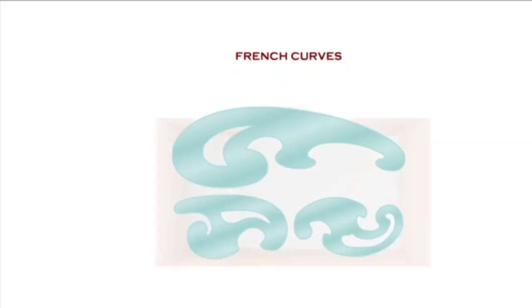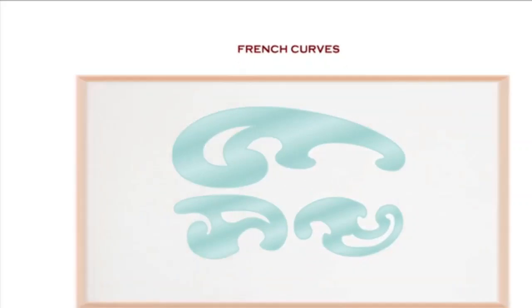Now we will move toward the French curves. Why are these French curves used? In engineering drawing, at some points we have to draw smooth curves. Smooth curves cannot be drawn by using a compass, divider, or the mini drafter. So for that, French curves are used.